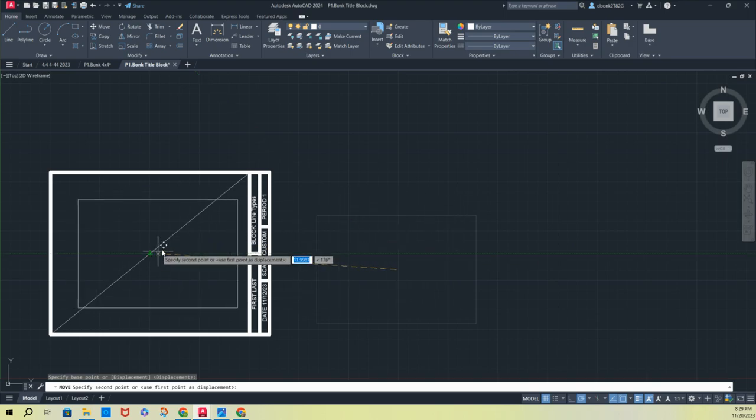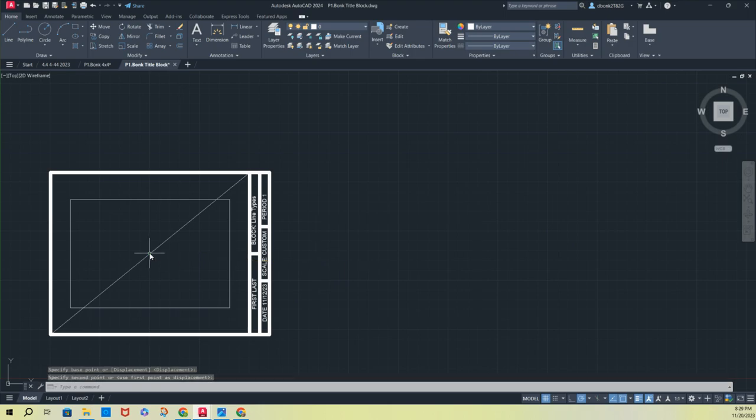And then you're going to put it over and you're going to find this X in the center of the middle of the block. You're going to find a triangle in the middle of the line. Click when you lay the two on top of one another. And that's how you center up this entire thing. And you get rid of this construction line that we just built, this diagonal line. Just click on it, hit the delete key on the keyboard. When people hit backspace instead of delete all the time, make sure you're hitting the delete key on the keyboard.